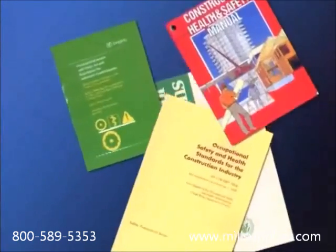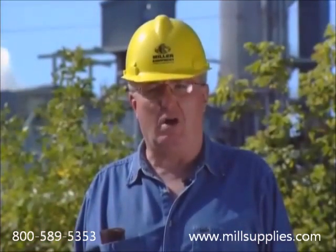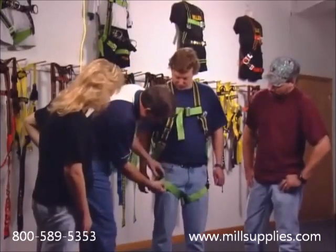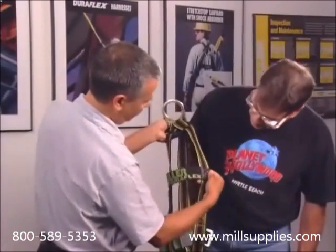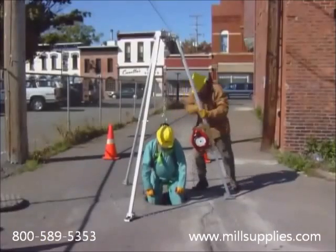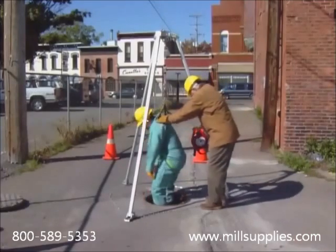Safety regulations governing your particular work environment are set forth in publications offered by OSHA and ANSI in the U.S., and in Canada by CSA and the provincial governments. You should be sure to obtain copies of all applicable regulations. All workers must be trained in the proper use of fall protection equipment before attempting to use any fall protection products. Employees must also receive instruction on inspection and maintenance procedures, as well as the proper way to wear fall protection equipment. Rescue plans should be developed and rehearsed in such a way that each member of the rescue team understands his or her responsibilities and has developed the skills necessary to perform the individual tasks required.